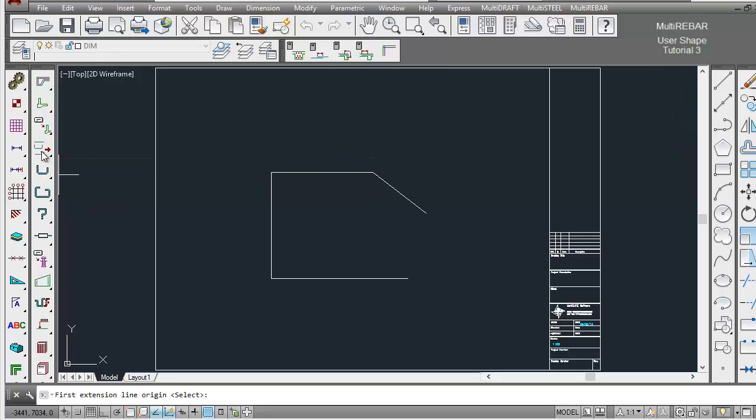We could pick the start and end points of lines, or we can enter or right mouse click to access the Select option. We can now select which of our lines require horizontal dimensions. We can then return to access the command and place our other horizontal dimension.